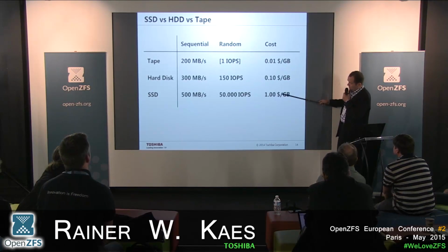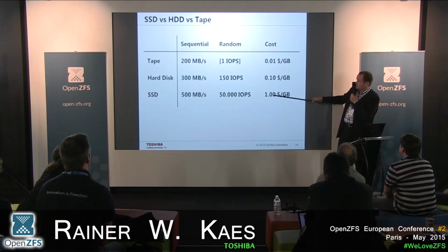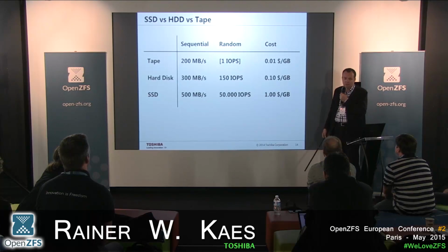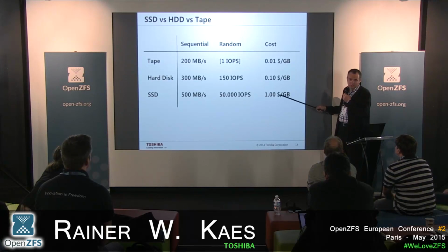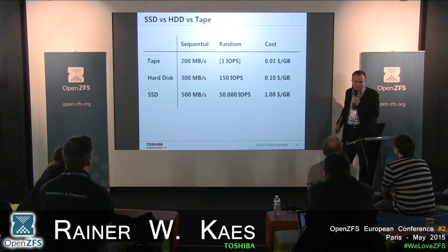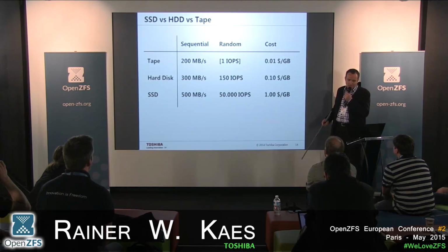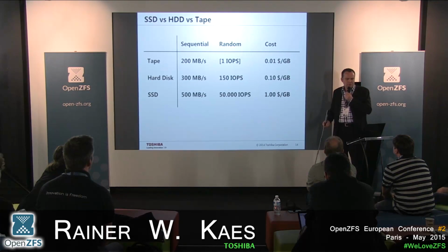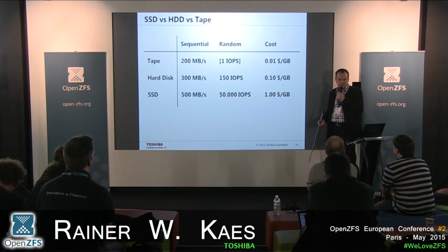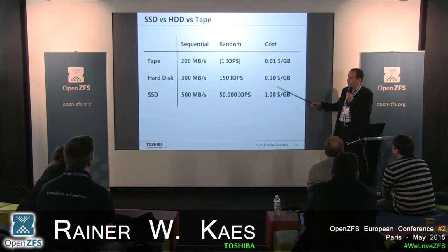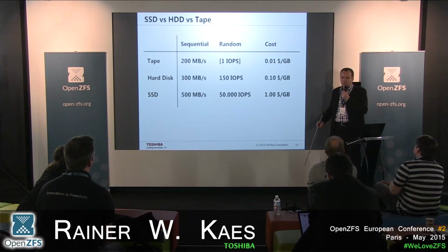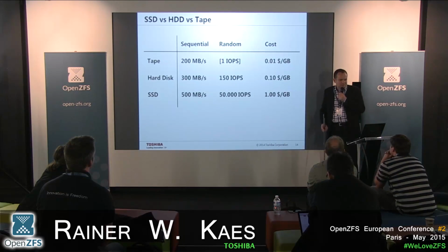And at the moment, there is this ratio between SSD and hard disk in cost per gig, but we are seeing SSDs approaching the 20 cent, 15 cent, maybe 10 cent per gig, but at the same time, we are seeing that with shingled magnetic recording and bit pattern media and all these hard disk developments, they will be at 1 cent per gig when there are 10 cent per gig there. So they will coexist probably until I retire.